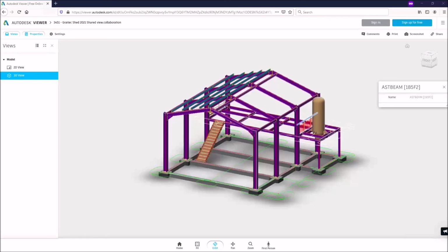Tim has just said as well, he automates the QR code in his GAs. He uses the project data properties to fill in the site address and the link to the model, and then both the codes show up on the drawing. And I think there are, on the Autodesk forums and the Advanced Steel Facebook page online, different threads and links for people using QR codes in different ways. You can even use QR codes on part drawings and assembly drawings. You can create a bill of materials that has an automatic QR code to print off and stick on the beams.